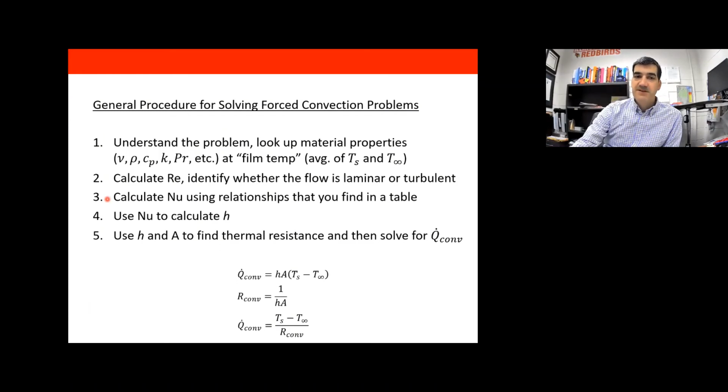And the next step is you use the Nusselt number equations that I haven't given you yet, but I will. I'm going to give you some Nusselt number equations to find the Nusselt number, mostly based on the Reynolds number and the Prandtl number. So for different types of geometries, different types of situations, you'll calculate the Nusselt number. And then after you've completed calculating the Nusselt number, you'll use the definition of the Nusselt number.